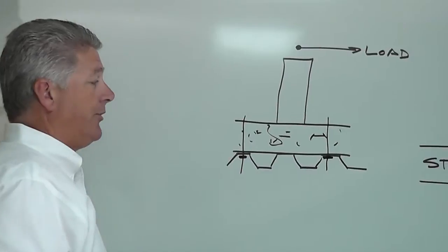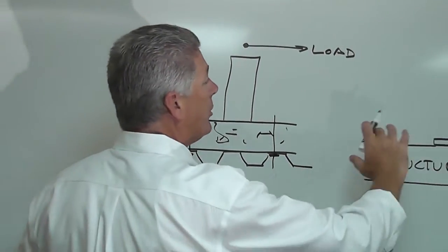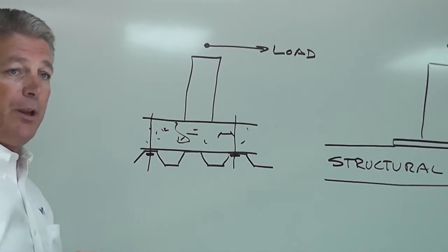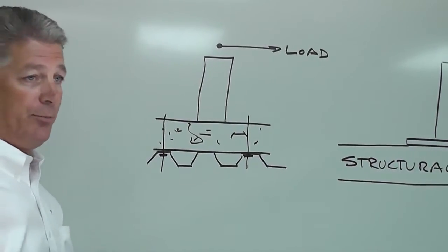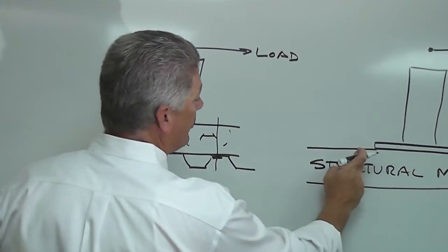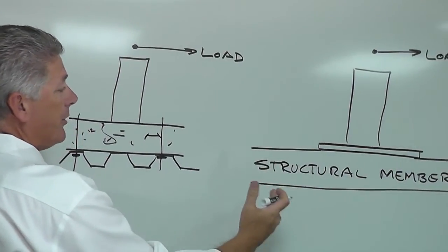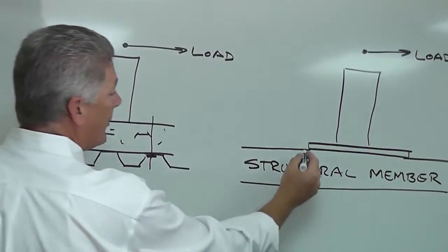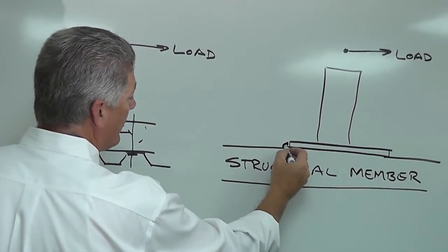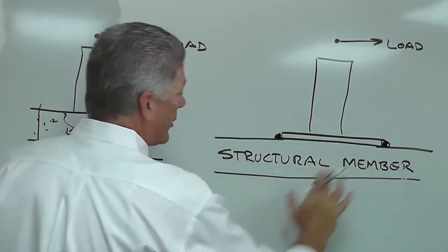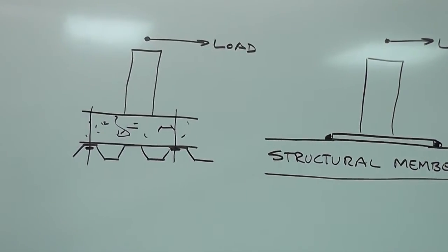On a rigid post design, you would have to have a much larger opening, which is more invasive to the roof, because you have to cut the roof open at this point to expose the structural materials on the underneath side. When exposed, there's different types of mounting. A typical type of mount would require some type of weld to weld the base plate of the post to the structural member that you're attaching to.